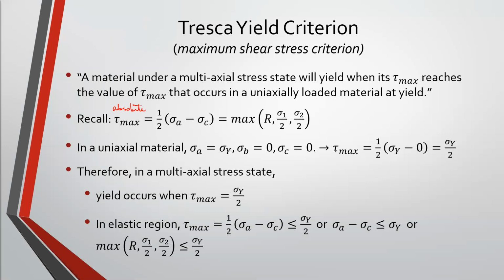And so let's take a look at what that looks like for uniaxial stress. What does your Mohr circle look like for uniaxial stress? Okay. And what are the two normal stresses? What are the two principal stresses? Yes, you're being so general, but you are absolutely correct. Yeah, we have sigma average as the center, sigma 1 and sigma 2 are our principal stresses.